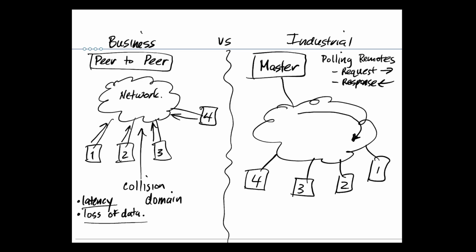When we look at Modbus, Modbus is a master-slave, or maybe the more politically correct term these days is client-server, where we have a client or master continually polling each one of the slaves or servers within the network in something called a polling sequence.